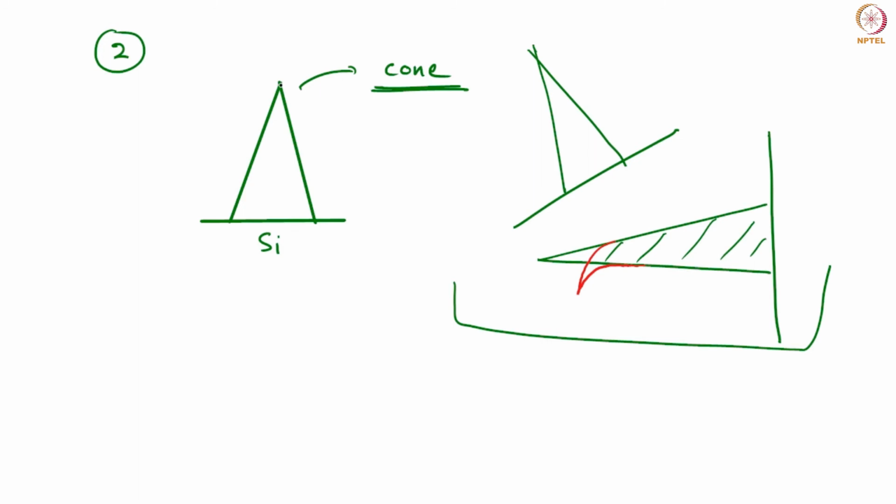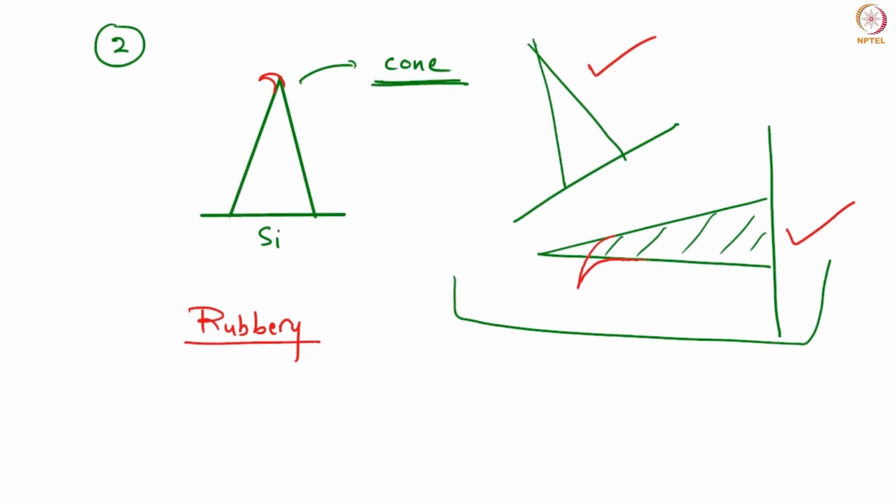Okay, or even if the polymer goes through too much of a liquid state, so not a semi-solid but rather a viscous liquid type state, in that case, even when your tip is standing up, you will find some sort of bending. But if that is not the case, because in most cases there are many polymers, they just go through a rubbery or semi-solid, whatever you want to call it, rubbery state, not a liquid-like state. So in that case, you will need to place your sample in such a way that you can observe some sort of deformation afterwards.